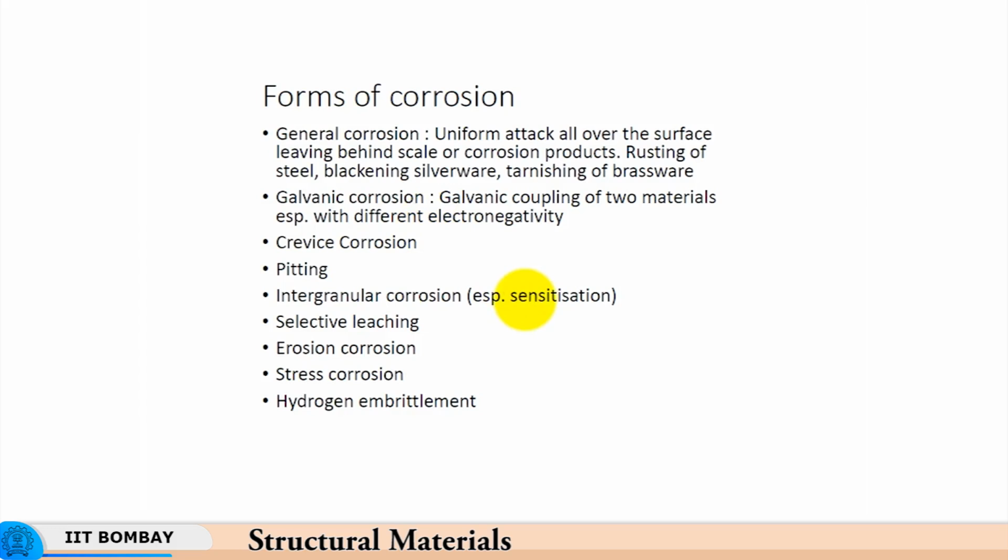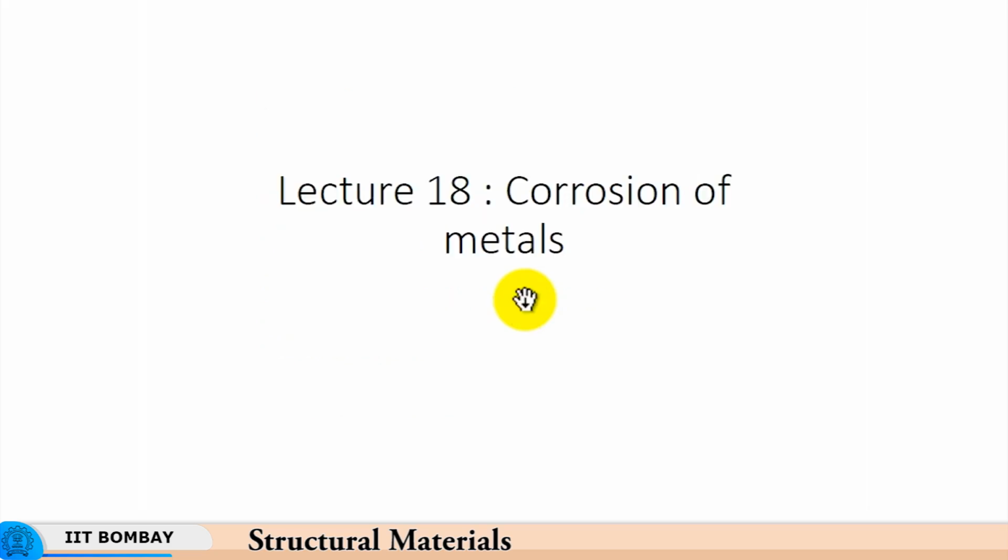Actually, aluminum is not attacking steel, nor is steel attacking aluminum. Steel is not soluble in aluminum, aluminum is not soluble in steel. So, there is an interface where you might have some intermetallics form, but that area is not the issue. The issue is the difference in the electronegativities between the two elements and the galvanic coupling resulting in corrosion of one of the elements.